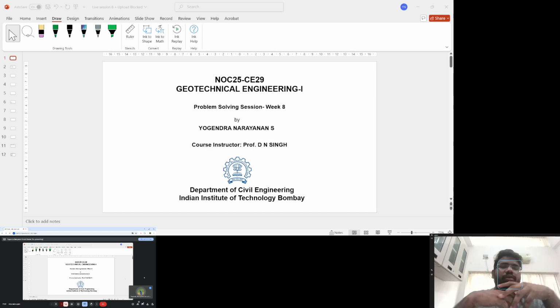So, with this, I would like to give a brief recap of what has been covered in the previous week, that is week 8. It was essentially on seepage theory and flow nets, especially the emphasis was given on flow nets and how to calculate the discharge from a two-dimensional flow through soil mass by using flow net. It is just an extension of one-dimensional flow and Darcy's law to the second dimension. Regarding this, we'll be solving some problems.